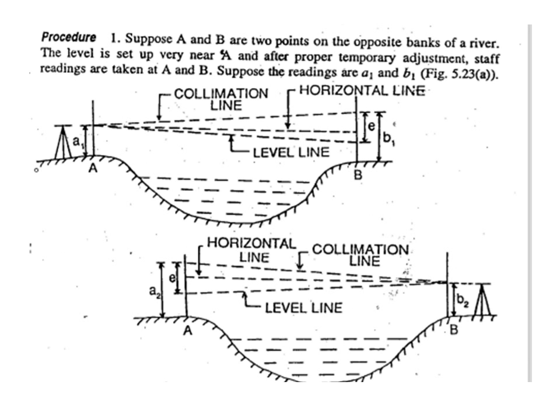In this slide we are going to see the case when the line of collimation is inclined upwards. Let A and B be the 2 stations whose true difference of level is required. The level is set up at O as shown in the figure, exactly midway between A and B. Let alpha be the angle of inclination of the collimation line with horizontal, and capital A small a the true reading at station A, and A A1 the observed staff reading on A. Therefore, the error observed on station A equal to A A1 minus A a, that is equal to d tan alpha.